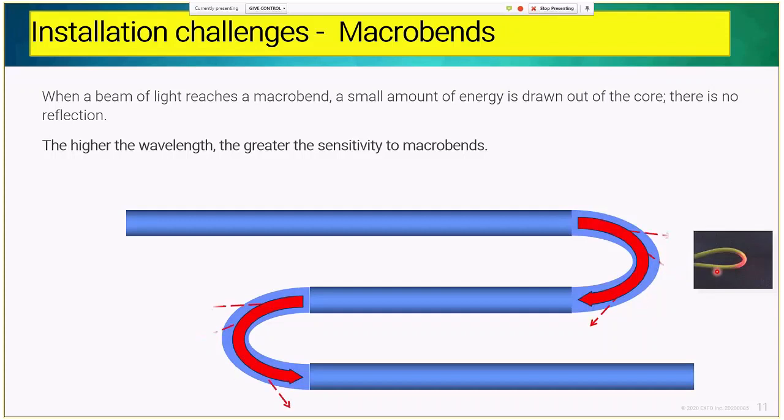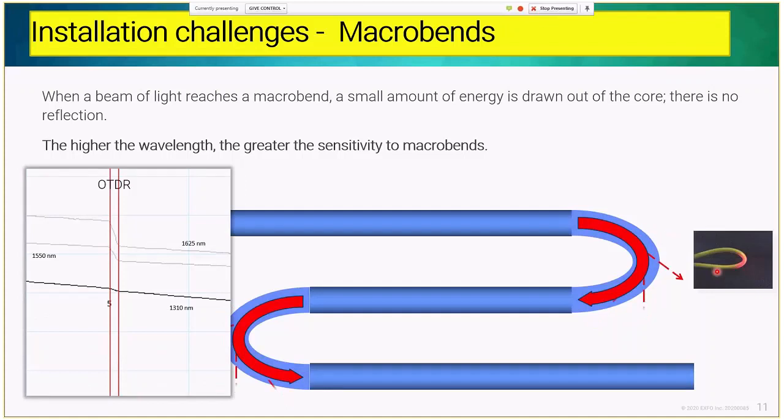Why is it so important? The detection of macrobends is extremely important because today we work at 1550, 1310, 1490. If you're not using RF overlay, we have the downstream and upstream inside of this band. But tomorrow, with the new applications coming, 10 gig PONs, new generation PONs, we are going to be working much higher, in the sector of 1600, just below 1625.